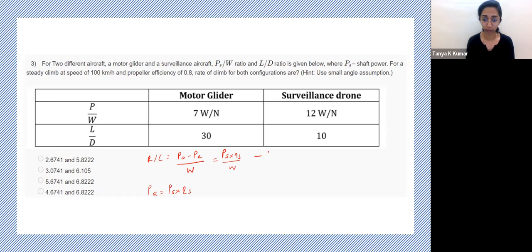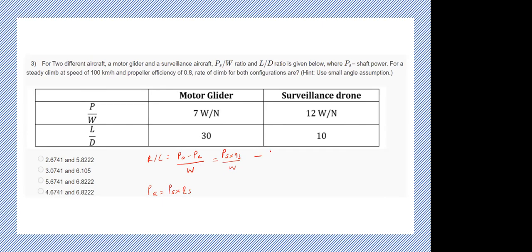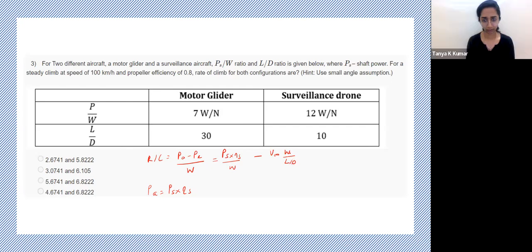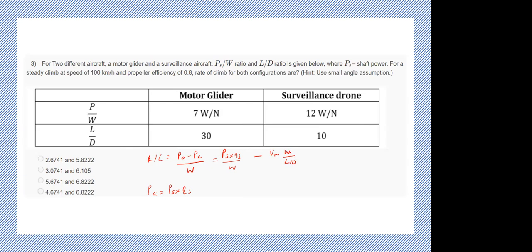What is the power required? V infinity into weight upon L by D. Isn't this just thrust required? You can write that, right?